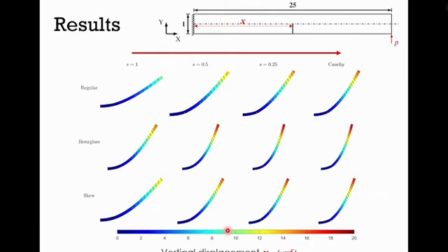This is a result for the vertical displacements U2 for all study cases in the deformed configuration. We can see that there is a scale effect on the result of the Cosserat continuum. As the scale decreases, the result is closer to that of the Cauchy continuum.